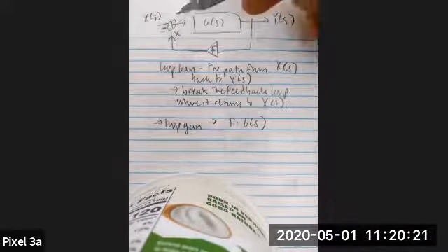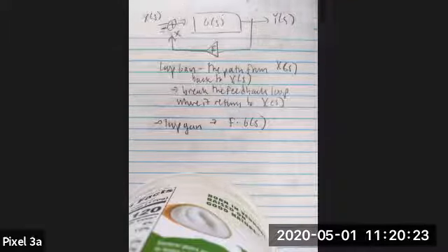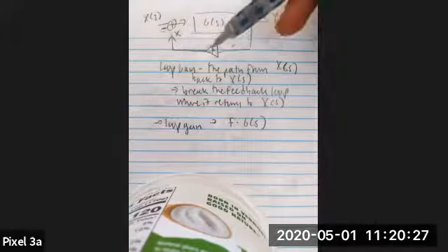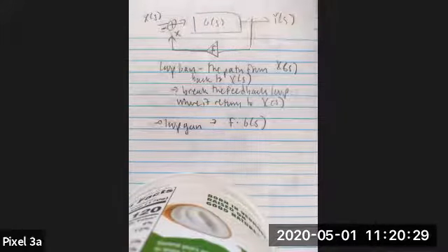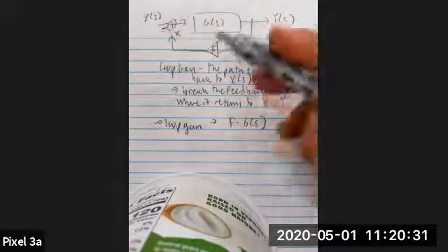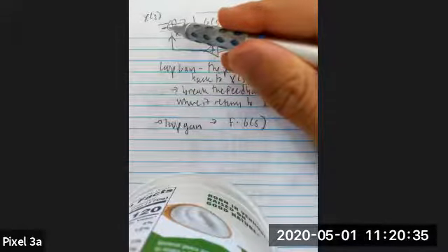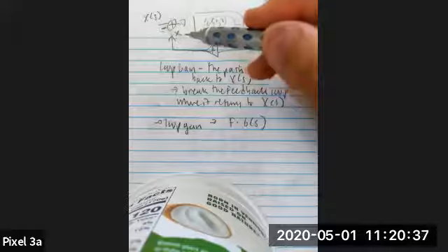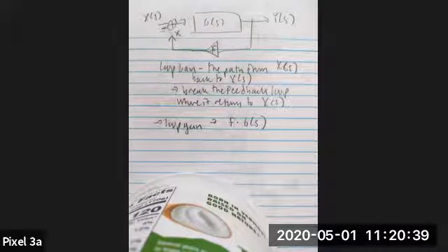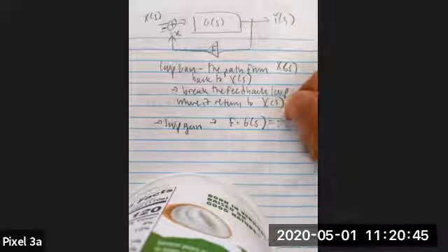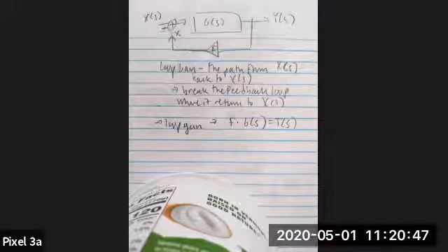So we see that x first goes through g of s, and then it arrives here, and then to get back to x of s, we go through a gain of f. And so, in some definitions, we include the minus sign here because that isn't assumed in the system model. But in this case, we're going to generally just assume that the minus sign is included. So we're just going to call this the loop gain, which is T of S, or T for short.